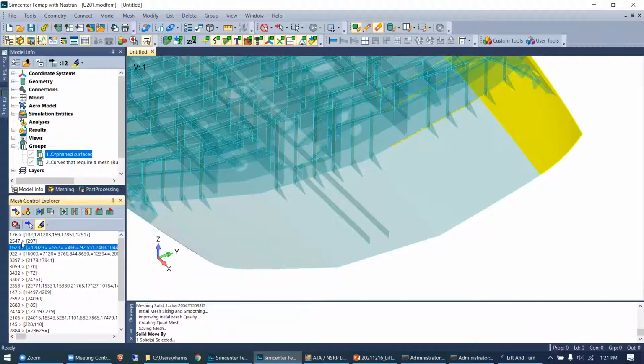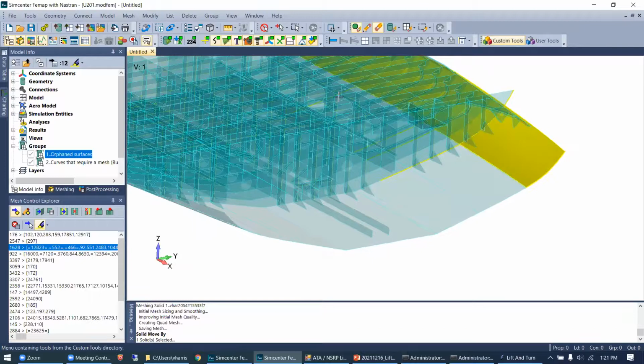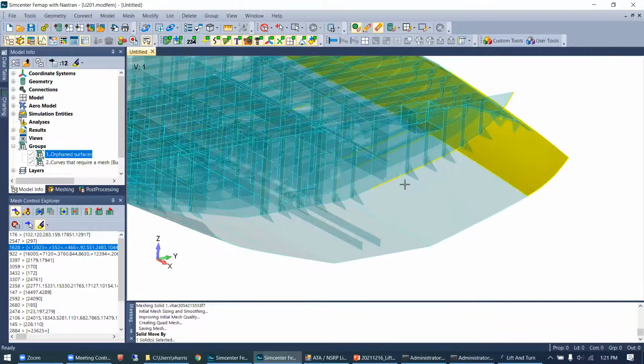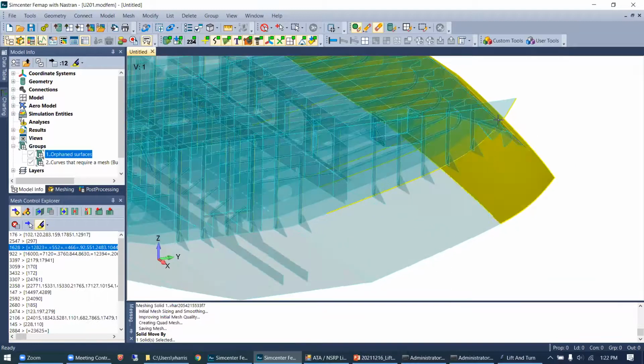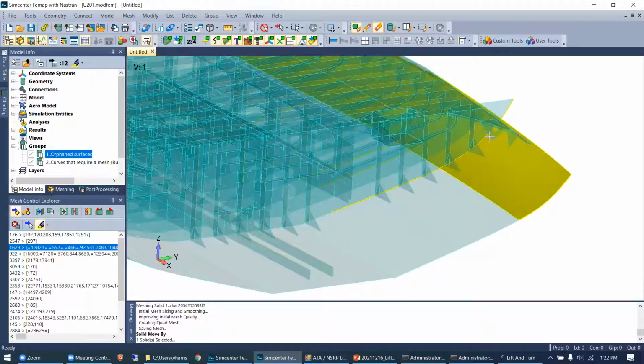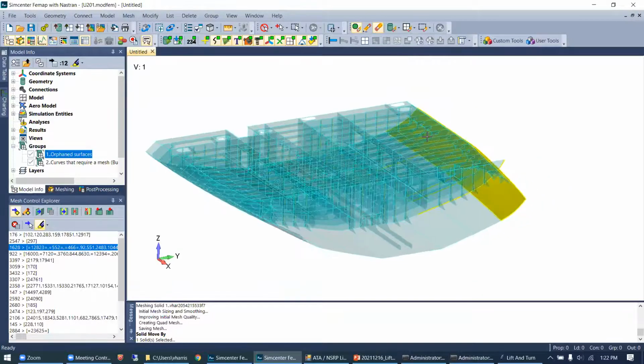Let's see, this one, you can see I've got this face over here, has found some of these stiffener edges inside the structure. It thinks that these two, this curve and this face, should be paired, and they aren't right now. So as I said, I can come in here and say imprint edges or imprint edges all, take care of the whole thing. So that is going to speed up the remaining 10% of this process for you quite a bit.